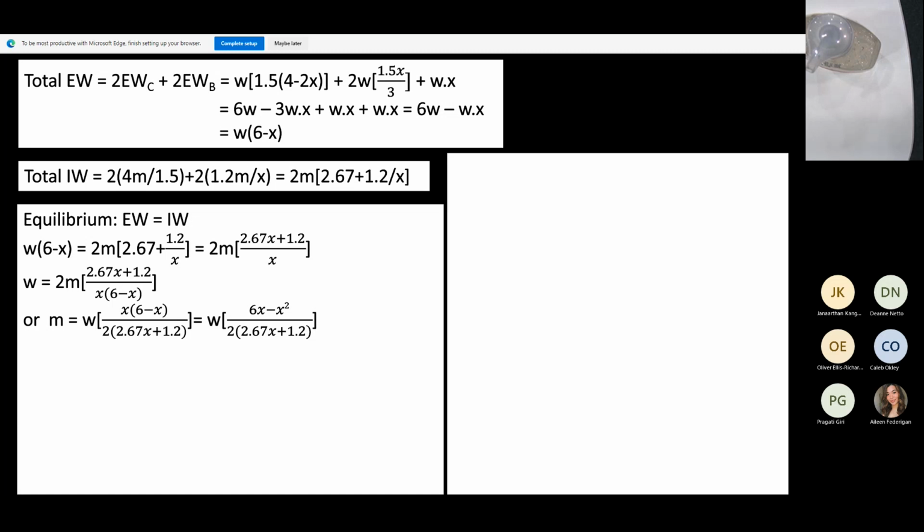So we've got what we have here. We've got the moment of resistance. The load usually is given. Usually you know the load you're applying onto your slab. So therefore, what we see here is that the moment m is actually a function of the distance x only. And remember, the distance x is unknown, so we need to find the value of x which gives us the optimum solution.